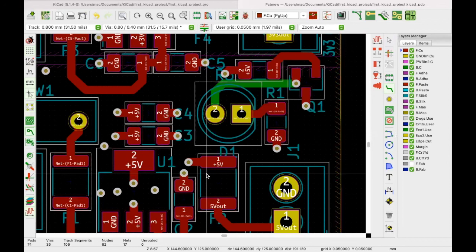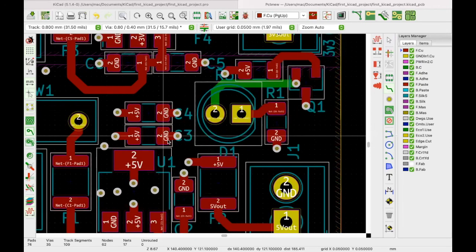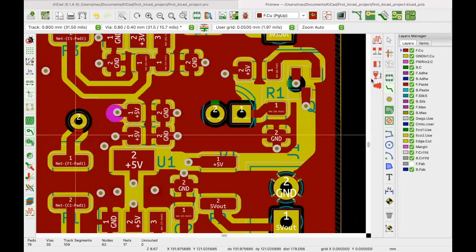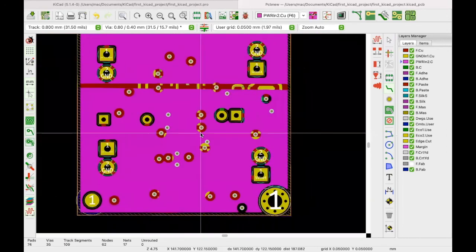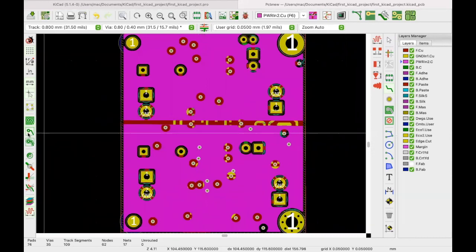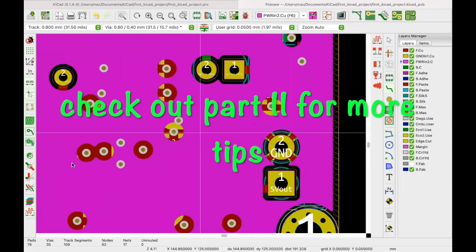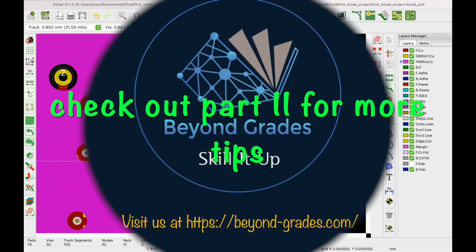And of course, remember, as we did on ground on the previous one, even if you have your ground as internal layers, you don't have to do manual routing and connecting all your ground together. You just have to do a small via to ground. You just drop a via anywhere and you have everything connected, as we are having it now here. So that's at least a practical way of how we can deal with stuff like this. Say one more thing here, I'll highlight one more thing here, and it will come out as a very interesting tool here.